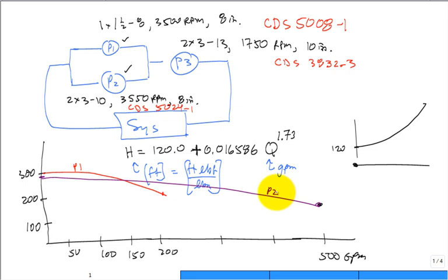So when you combine 2 pumps in parallel, what does the composite look like? It's as if the Q through pump 1 and the Q in pump 2 add up, but they have to have the same head gain. When it's running at steady state, the head gain across pump 1 has to equal the head gain across pump 2. True or false?